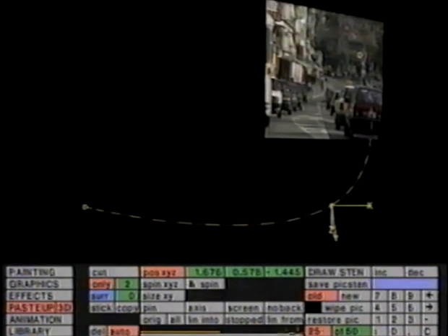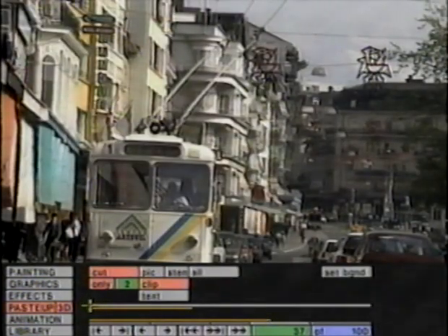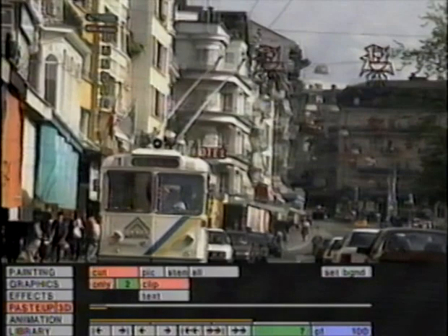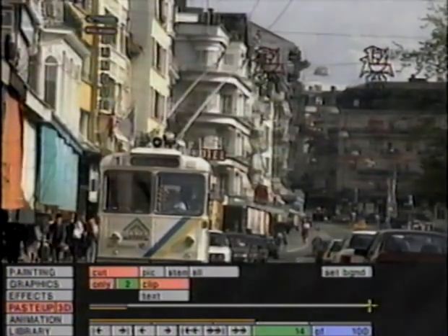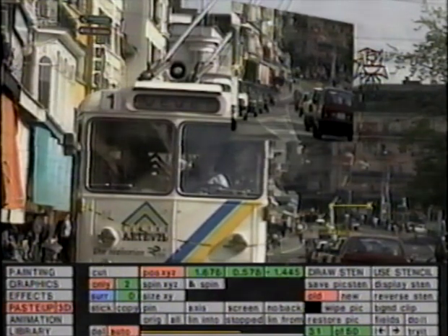By enabling the frame count box, it's possible to change the time at which the keyframe occurs. It's also possible to trim the start point of the layers on the desk. Everything is uncommitted at this stage. Layers can be added, deleted, priorities changed, or positions changed.